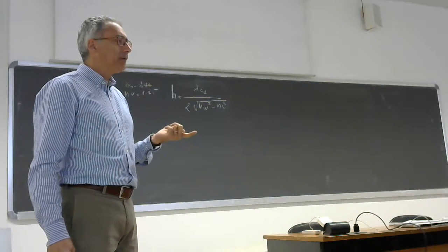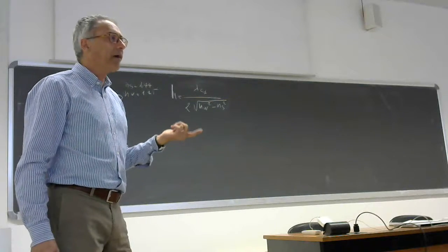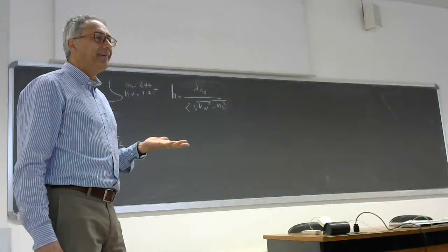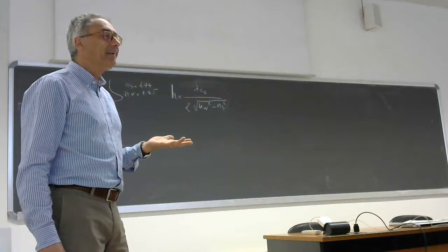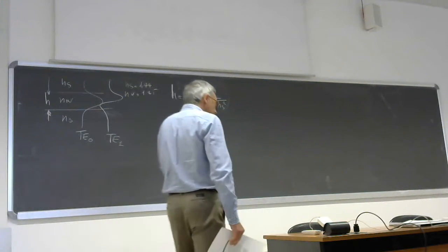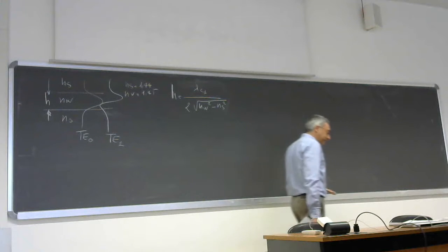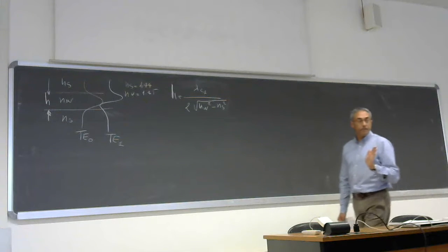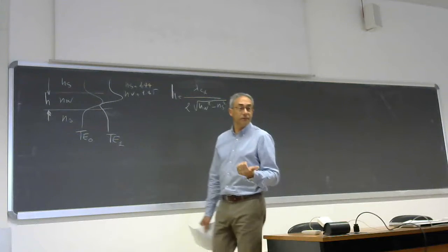Meters? Liters? Hertz? It is a symmetric slab waveguide, so the fundamental mode does not have a cutoff. So the cutoff wavelength is infinite. The cutoff frequency is 0.